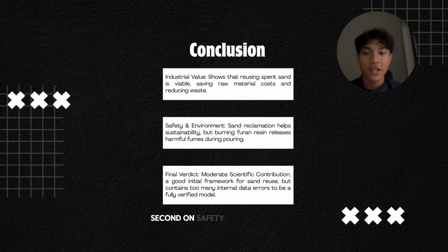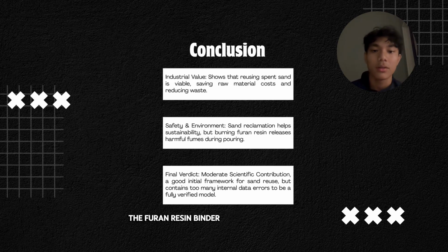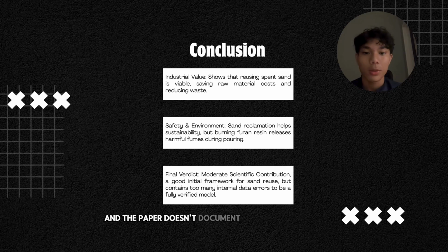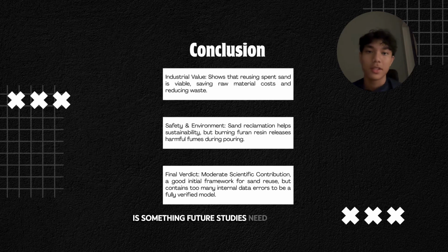Second, on safety and environment, while sand reclamation supports sustainability, it isn't without concerns. The furan resin binder releases harmful fumes when it burns during pouring, and the paper doesn't document any ventilation or fume extraction measures, which is something future studies need to address.